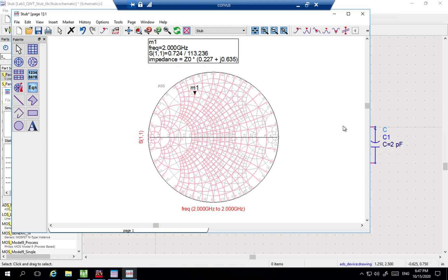Okay, so that was a lot of talking, but we can actually go ahead and do that now with a microstrip line. Okay, so part D is done. We've simulated the load impedance, and we've plotted the S11 on the Smith chart, and now you guys can compare the values, and hopefully they should be almost the same. Okay, so let's go ahead and save that.